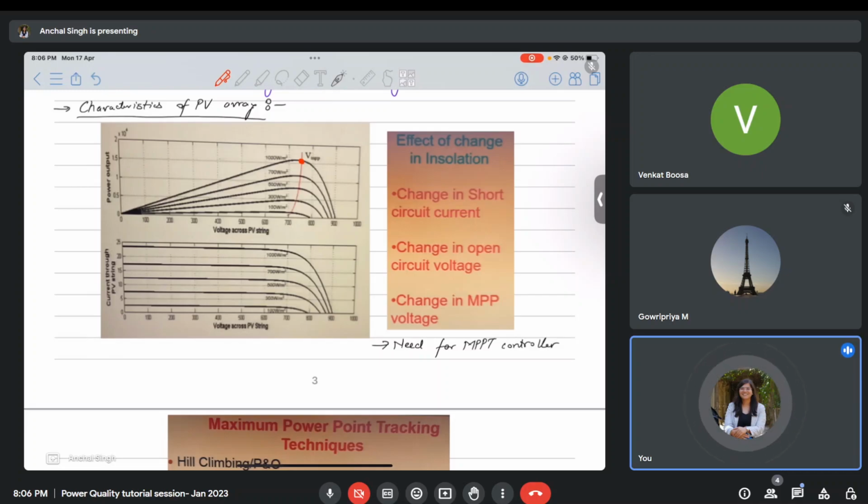So if you talk about this maximum power point, it corresponds to a particular voltage, right? Let me call it Vm. So if I plot this Vm on this curve, then there is a particular Vm and a particular Im here, right? So I will put in a closed loop, and using the closed loop control, I will draw this Im amount of current from my solar panel, so that I operate at maximum power point. That is the goal.